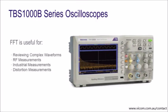For example, you can use the FFT for radio frequency analysis of radio transmitters, as well as for vibration analysis of mechanical devices. You can also use the FFT to analyze the distortion of a sine wave being generated by a circuit.